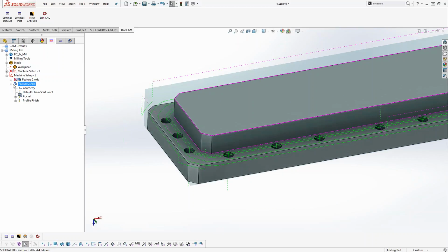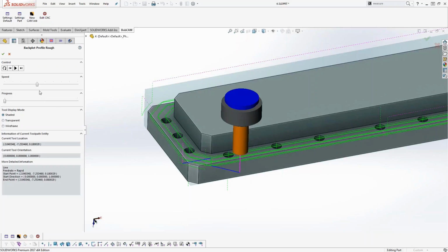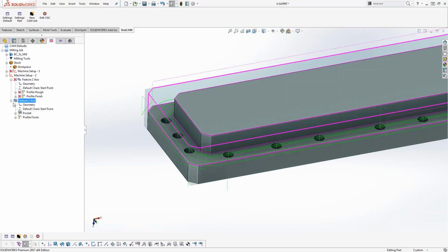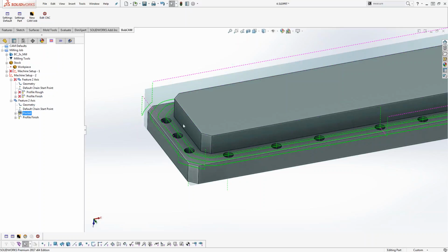So, side roughing is one way to accomplish this, where we tell it how much material and how much per pass. You have to measure. Sometimes there's some guesswork, and if it's irregular thickness around the part, it may not be the best scenario for you. If you are using open pocketing, if you have a surface shoulder like this, it can pick up the edge of the stock and actually do an open pocket.